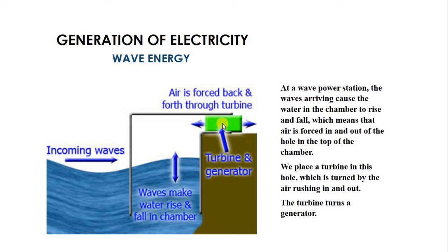No. The pitch of the turbine blades is designed in such a way that whether the air is going right or coming left, the turbine blades will continue in the same direction. So when the water rises and falls, the air is pushed out or sucked in, the turbine will still be turning in the same direction and power will be generated.